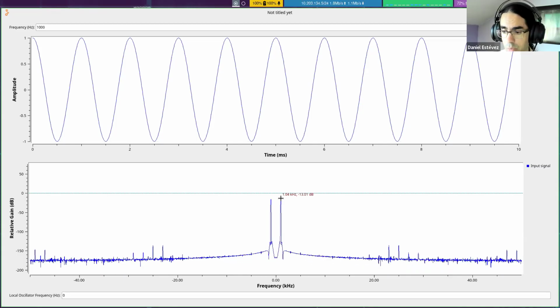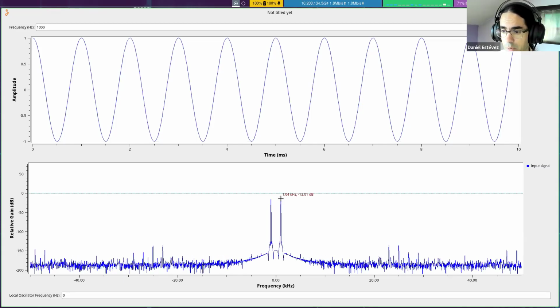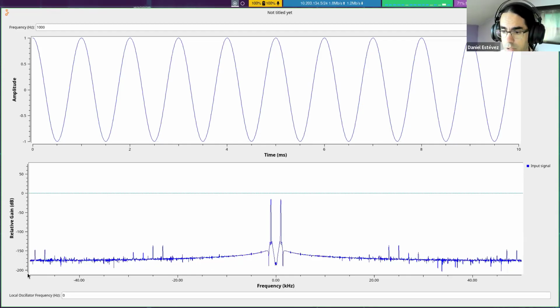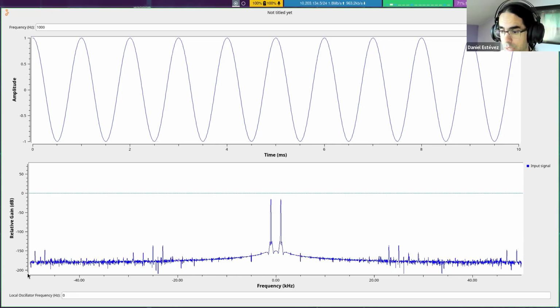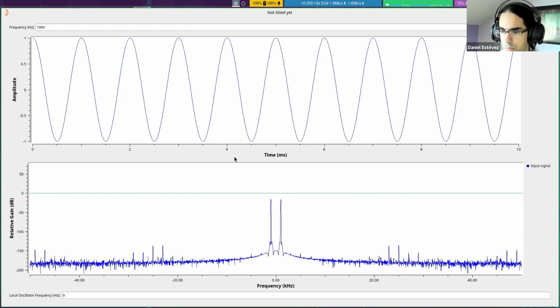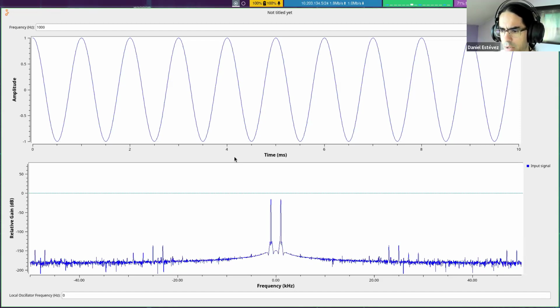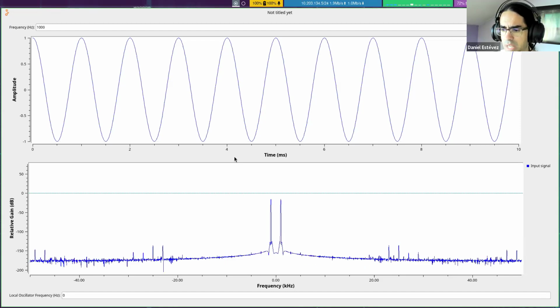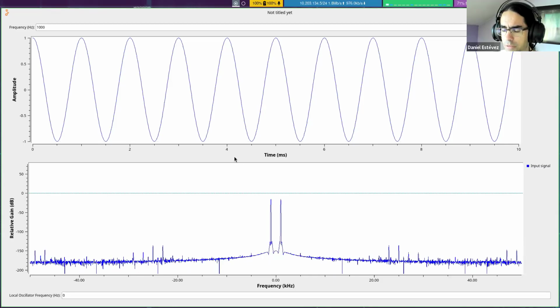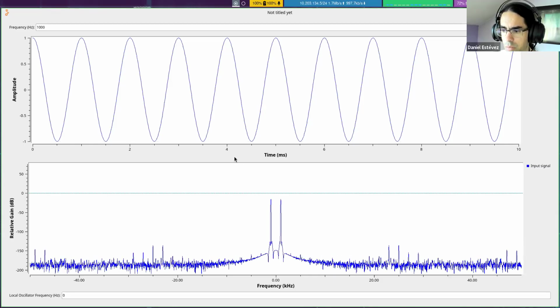So the negative half of the spectrum is actually mirrored, and it doesn't add any new information. That matches our physical intuition, because this mirror thing appears just because the mathematics requires it. At this point, nothing too complicated, and complex numbers have only entered the picture because we want to compute an FFT, to show the spectrum of the signal.